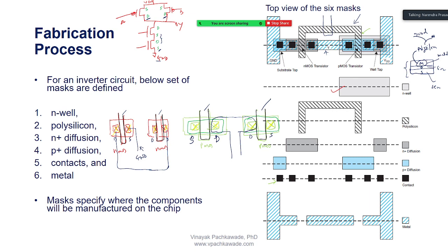Okay, sir. And in manufacturing, do they always use poly to connect gate to gate only? Right. For other connections, normal connections, they will use metal. Yeah. The gates will always be formed with polysilicon. Every transistor will have its gate made of polysilicon. It may be possible that two gates, let's say for instance you have A and B here, right? You have a polysilicon deposited here. It may be a choice of a designer based on some particular design need. There could be a metal connection connecting the two polys together.